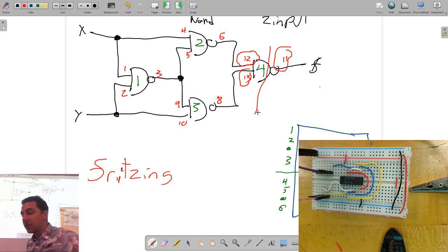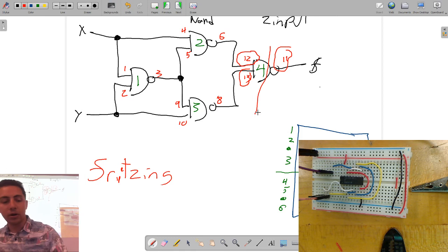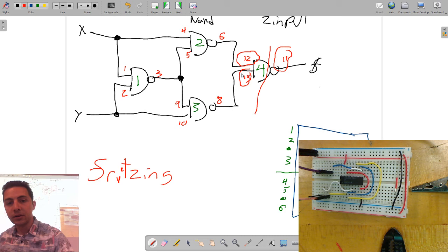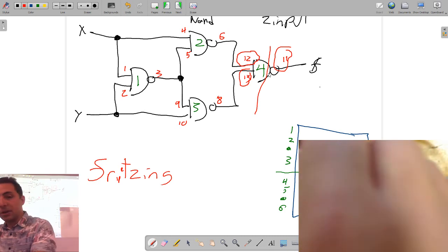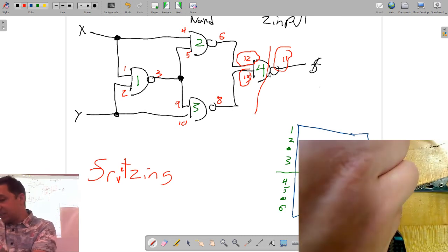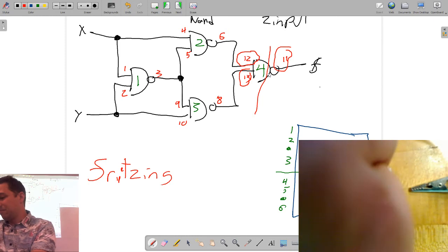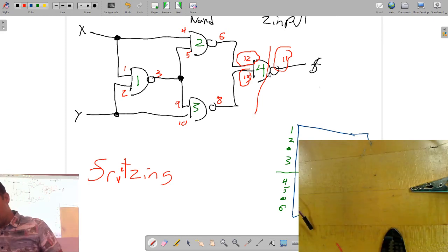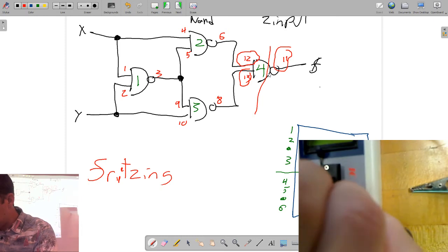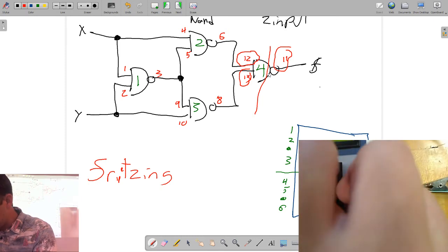Now I have up here a chip tester, okay? And I could take this chip out after turning the power off. Go back to waveforms here for a second. Turn the power supply off. All right. Carefully take the chip out, and I stick it in my little chip tester.